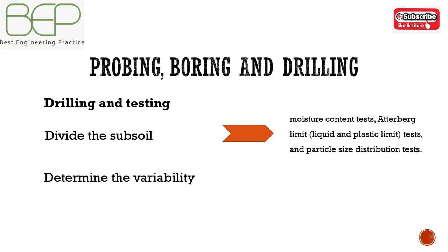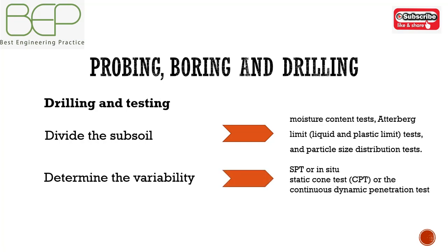Second, to determine the variability of each soil type or group. In addition, the results of in-situ tests such as SPT or in-situ vane tests are very useful for assessing variability. Even better, however, are tests which give a more or less continuous record with depth, such as the static cone test or the continuous dynamic penetration test. Third, to obtain parameters representative of each group for design purposes. All of these activities are normally carried out.